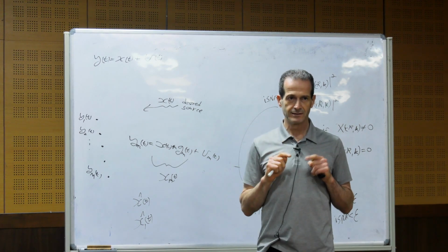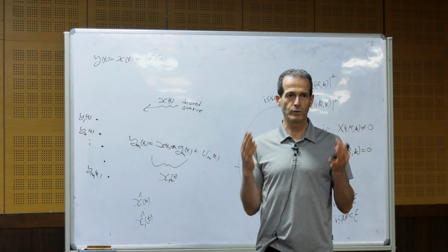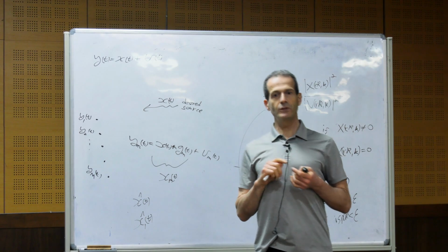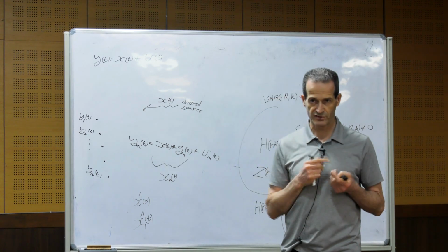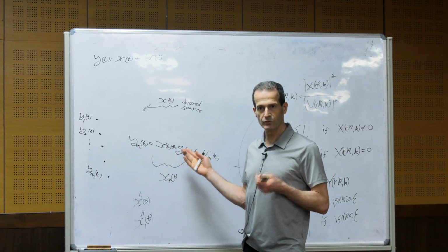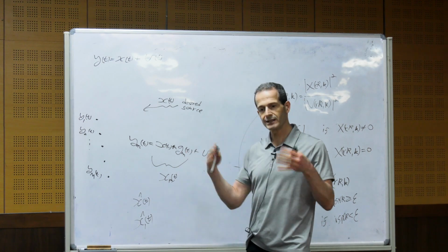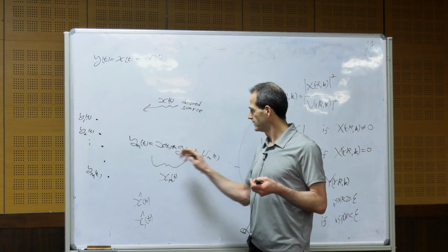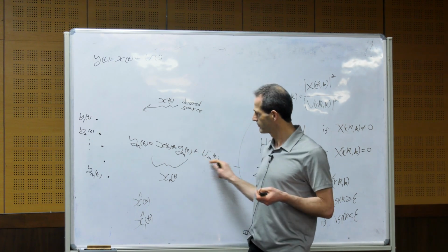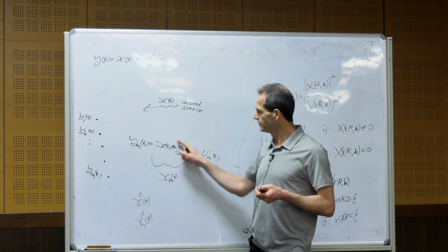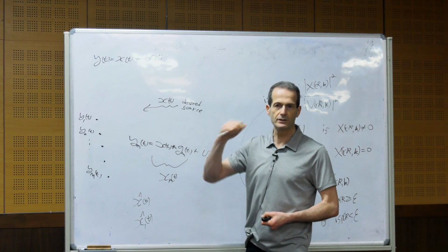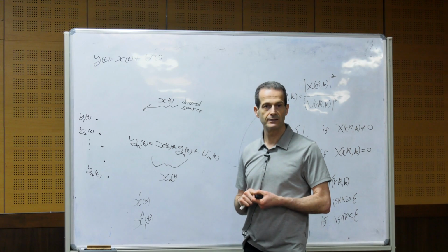The problem is, what will happen with deblurring? The noise will increase. So there are some trade-offs between noise reduction and deconvolution. If you try to do strict deconvolution, if there is no noise, it's much easier. But if there is noise, direct inverse of deconvolution generates or increases the noise very sharply.